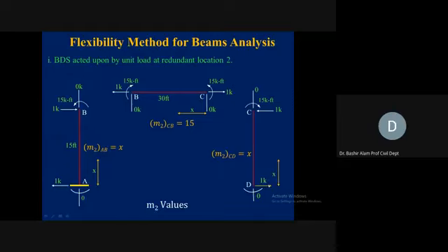So rightward directed 1 kip, we are applying at D now. Because of this, we are analyzing the whole members and the whole joints. How will we analyze CD? This was 1 kip rightward directed, so at C it is 1 kip leftward directed. Horizontally, the members are in equilibrium now. Vertical 0 here, so 0 we have here also. Now this 1 kip and 1 kip, it is causing a couple now. So 1 times 15, it is causing a counterclockwise moment. So by a clockwise moment, we need to balance it. So 15 kip-ft for this moment I'm putting at C now.